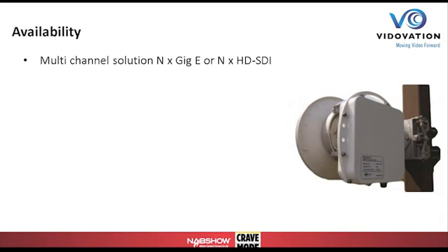So the receiving antenna horn has isolation. One element will only see the 0 polarization wave as the wave comes at it this way. The other polarization element will see only the wave that way. So we can kind of co-locate 2 radio waves on the same frequency, or if we combine slightly different frequencies with polarization, we can get better channel isolation to co-locate or cooperate, multiple paths through a given link.